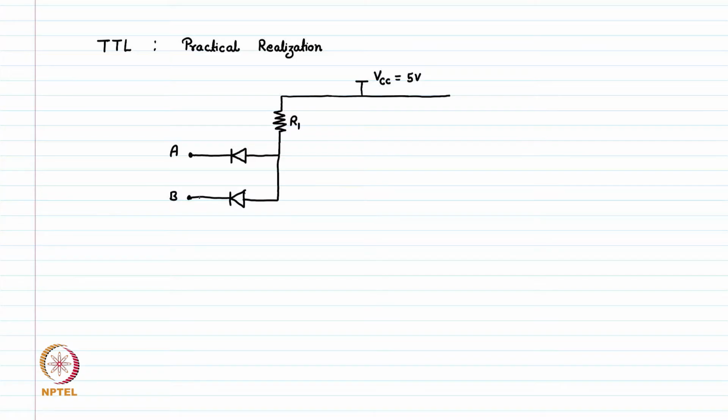We need to protect our input terminals from that high voltage stress. So, for example, this is the ground plane we have. We need to connect certain Zener diodes for the protection at the input. So this is the Zener diode.